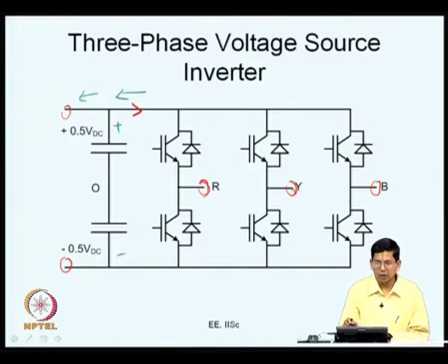If you look at it correspondingly on the line side, what happens is the phase difference between the voltage and the current waveforms changes. When the voltage and the current waveforms differ in phase only within plus 90 to minus 90 degrees, power flow is in a particular direction. If it is beyond 90 degrees, or close to 180 degrees, the power flow is really in the opposite direction. So, as we saw earlier, this is a bidirectional converter.